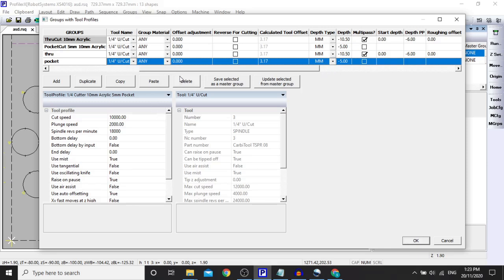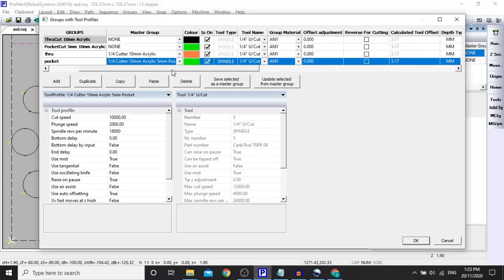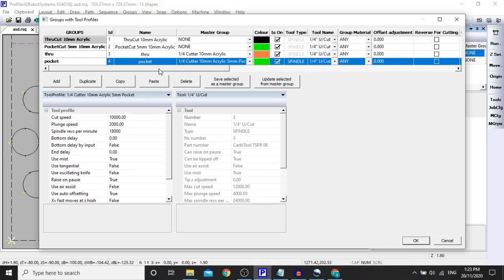Groups aren't constrained by master groups. Rather, it can be thought of that groups inherit their properties from the master groups. For instance, if we were to find that this particular piece of acrylic is chattering while cutting at a certain speed, we can refine this speed without affecting the master group, yet having the benefit of all the properties being brought over from the master group.